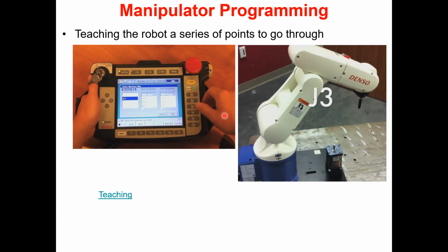And whether that kind of method is acceptable to the industry, the engineers or technical people, they'll have to sit in front of the computer, plan the trajectory, and then upload it. It'll work. That's not going to be the way it is. You need to have much more practical approach in the industry. So therefore, the manufacturers design this unit, which is called the teach pendant. Using this teach pendant, anybody with a little knowledge about the manipulator can program a manipulator.